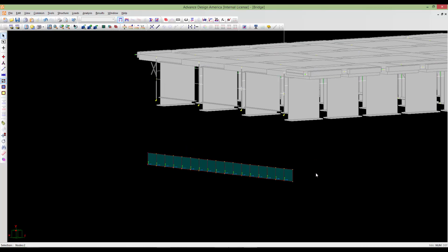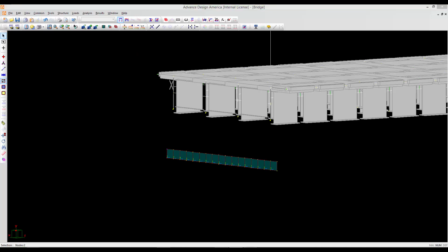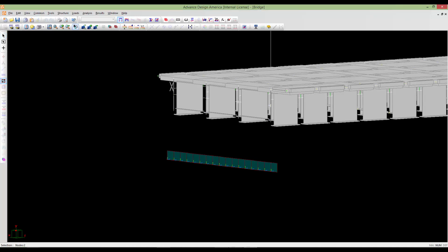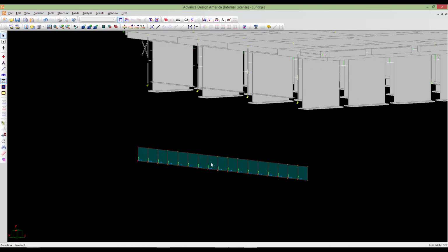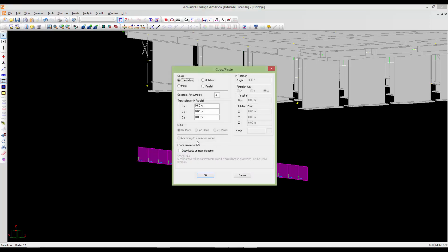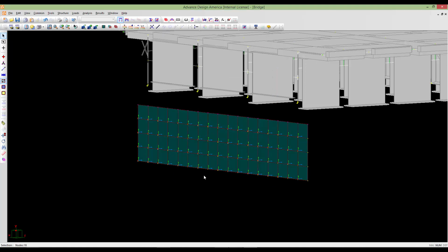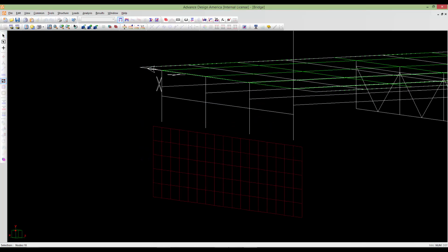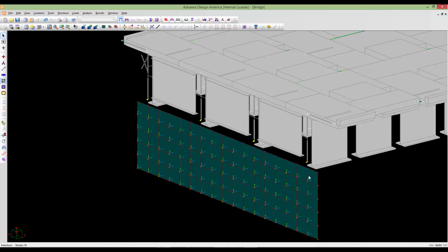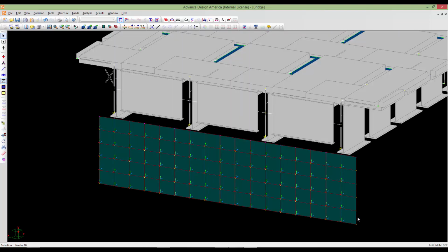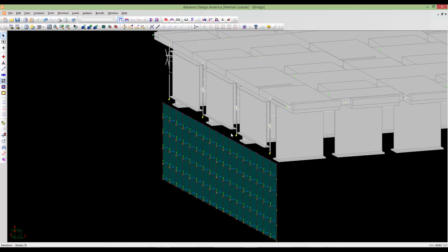And let's copy them again to define them in the vertical direction. In a vertical direction, I will copy and paste them 4 times to have a 2 meter wall. So select all of those, Ctrl C. In Y direction at each 0.5 meters. Okay, and Control V. So as you see here, I have my abutment wall, which is 2 meters in height.